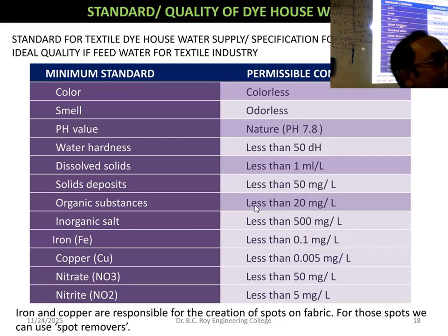Even in plastic pipe I have seen iron deposition at the junction. GI is getting damaged and swollen, plastic will not get damaged that way, but the deposition is still there. If iron is there, it will be deposited at the junction, wherever there is a joint, as brown color. That is practical experience I am telling you. Not that it is supposed to happen or not happen. I have seen this happen.